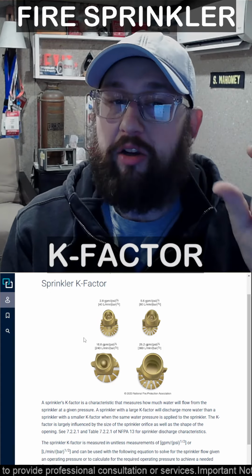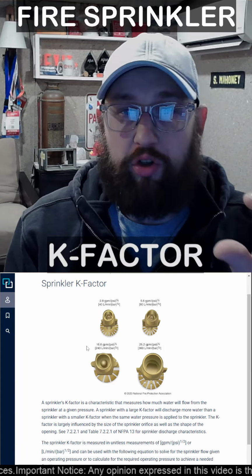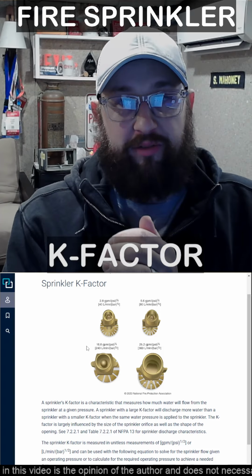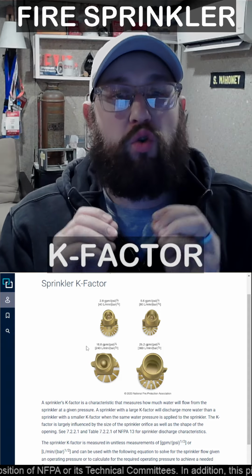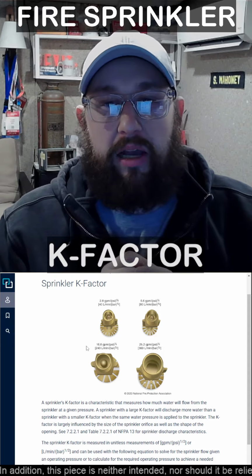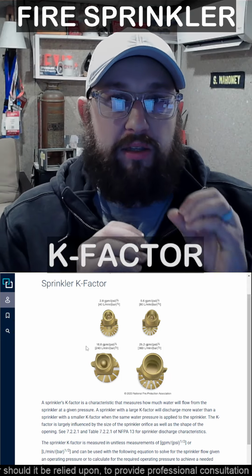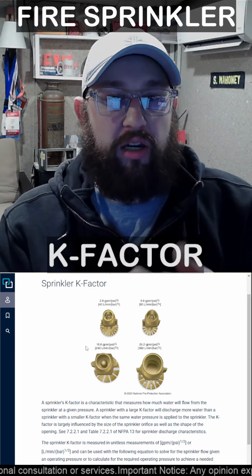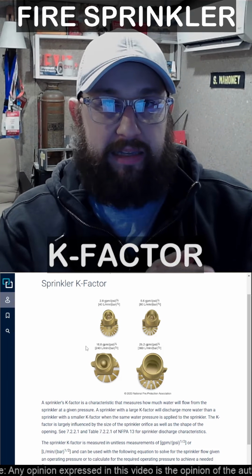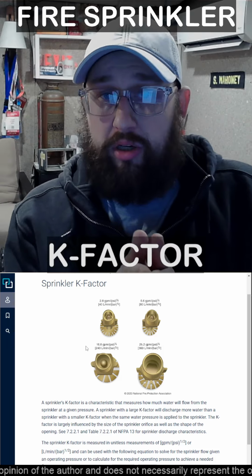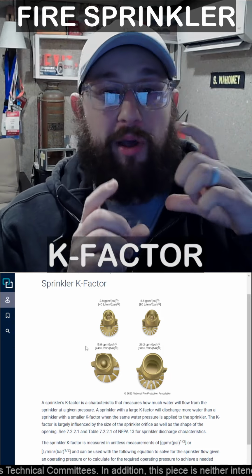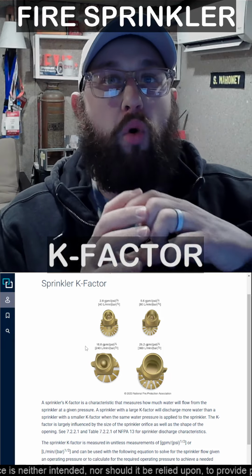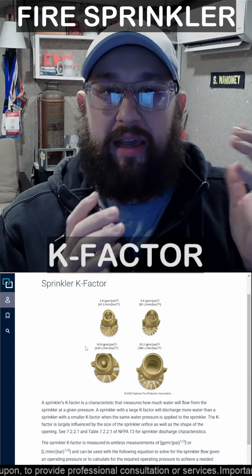And the sprinkler K factor is essentially a unitless measure. It is gallons per minute over the square root of PSI. And it is essentially a way to measure how much water is going to be flowing out of an orifice at a given pressure. So the bigger the K factor, essentially the bigger the opening, which means more water is going to flow out of that opening at the same pressure.